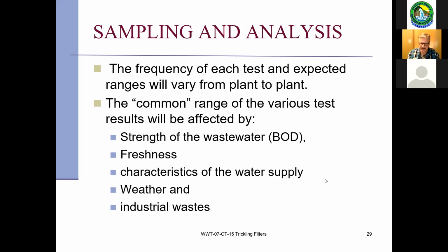So you could see there were parts of that filter forever regrowing all the time, trying to get that biomass. Luckily, as the flow came through, it dispersed through that line and hit the outside of the dispersion ring. So we used to lose a little bit of biomass on the outside, but the inside was still operating really well.